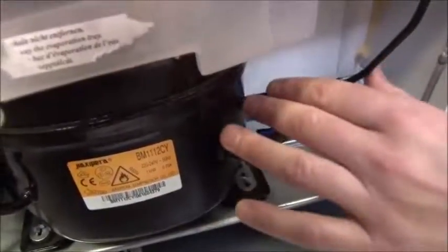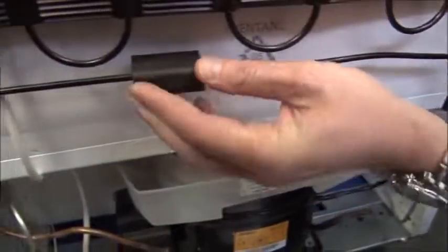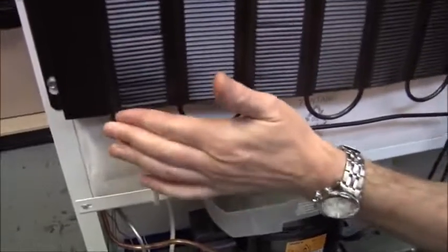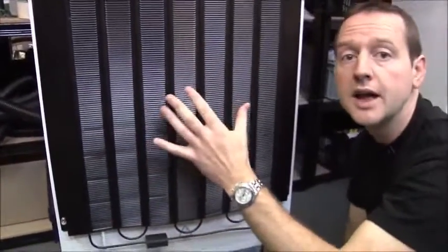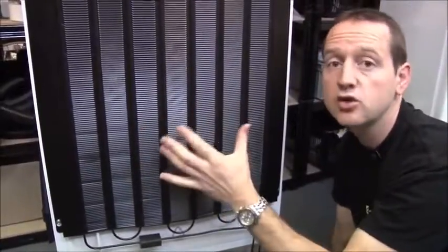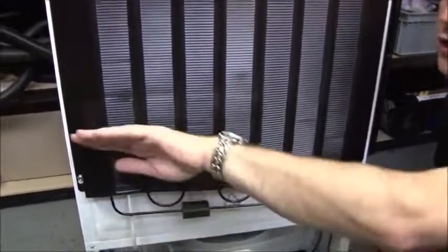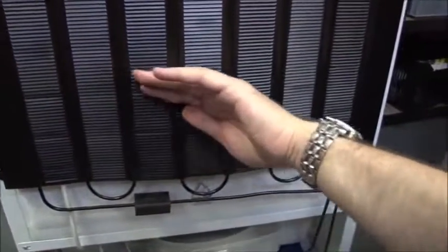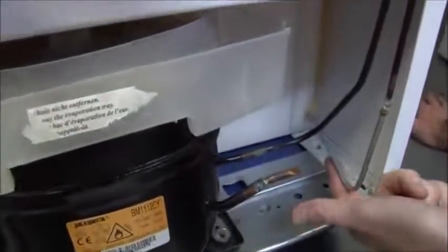So starting on the high pressure side of the compressor, our refrigerant gas gets very hot, much like a bike pump gets hot as you put the air under pressure when you're inflating a tyre. And that heat is radiated away in this condenser coil. It's like an ordinary household central heating radiator. And you can actually feel when it's on that it's very hot on this side, getting cooler as you move across, so that by the time it's over here, our refrigerant has cooled down sufficiently to be condensed into a liquid where it goes and sits in a reservoir at the bottom of the appliance.